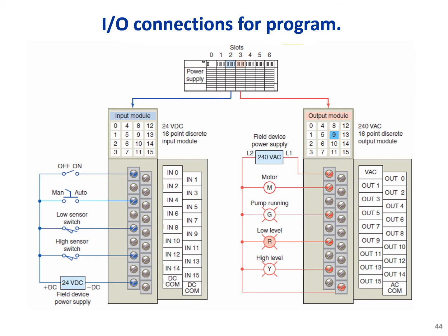Here, for example, the low level is on and is connected to output 9. You see the indicator light on the module is on. So we have LED indicators on the front panel of the input and output modules. It helps the operator or the programmer to diagnose and understand which input and output devices are on and off, and to either diagnose or improve the program and so on and so forth.